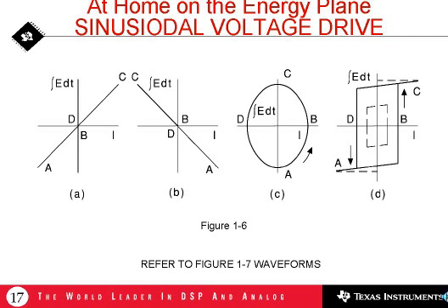Here we have a perfectly straight line going through the origin, and that represents an ideal inductor. Actually, it could be an air core inductor or a gap inductor. It's a straight line, and there's no hysteresis because the characteristic of any non-magnetic material is a straight line. The inductance is not changing. It's constant. The permeability is constant. There's no hysteresis. So that's an ideal inductor, which is approached by an inductor with an air gap.